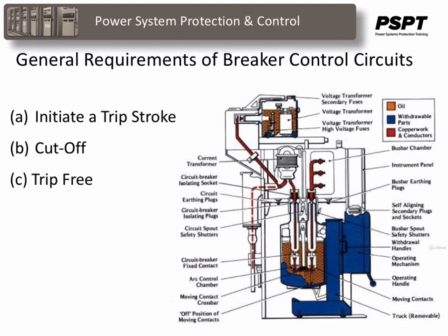Many motor-operated breakers obtain a fast trip-free action by use of a relay energized from the trip circuit to open the closing circuit. These methods would be known as mechanical trip-free, pneumatically trip-free, and electrically trip-free, respectively.